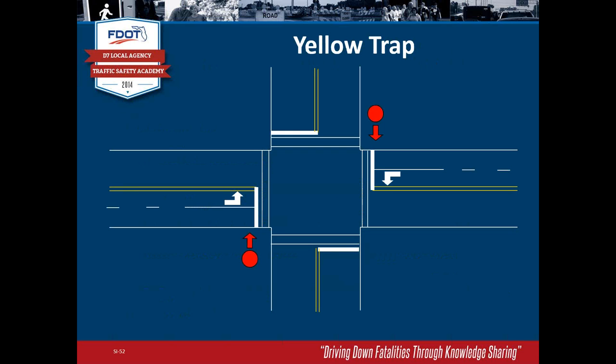So this is an intersection, and we're getting ready to start. We're just going to go through the east-west part of this. You've got a left turn lane in each direction and one through lane in each direction. And so here we start. Our one direction starts off, and we've got the green arrow going, so the left turn is protected here, and we've got the throughs going simultaneously with that. So we've got our eastbound lefts and throughs going together.